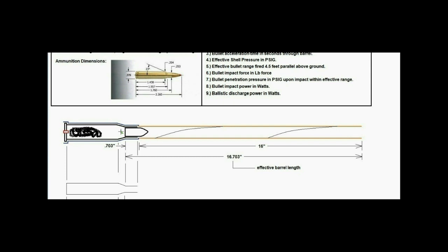So this then concentrates at the back of the bullet, its cross-sectional area. The pressure times the cross-sectional area will yield the force, the horizontal dynamic force, which then accelerates the bullet out of the shell neck, overcoming the interference fit, and then pushing the bullet out